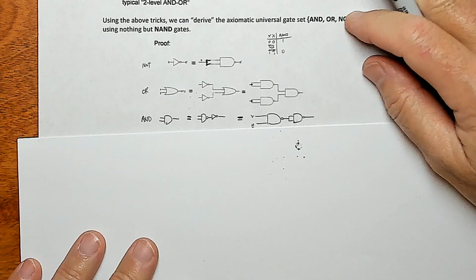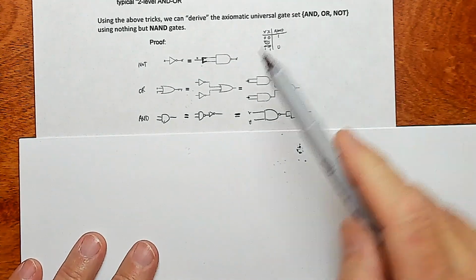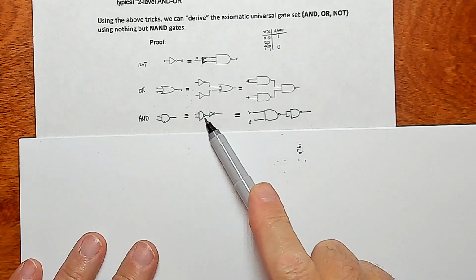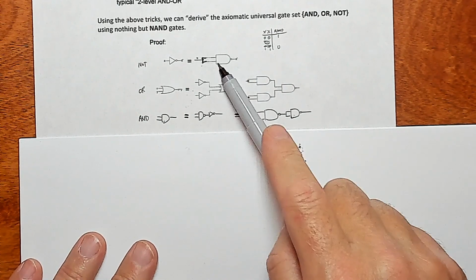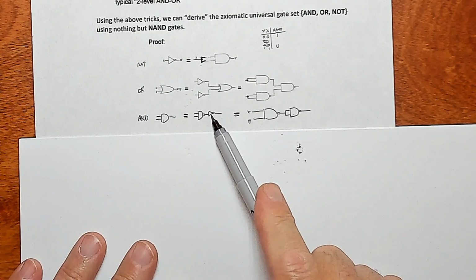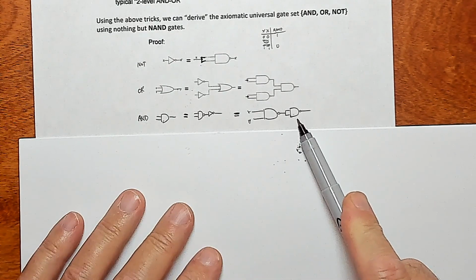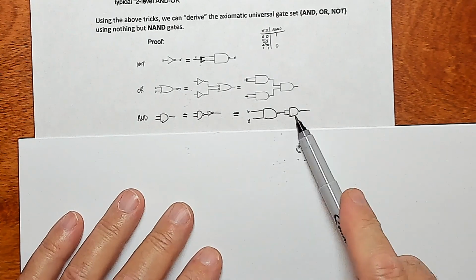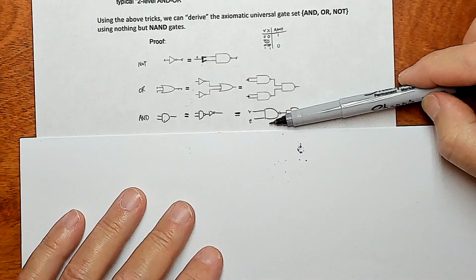Lastly, we can build an AND gate from NANDs simply by NOTing the output and then canceling that with the NOT gate, and then we've just shown up here that we can build a NOT gate out of NAND. So we replace the NOT gate with NAND. So we can build AND out of this combination of two NANDs, basically. So all you need is NANDs.